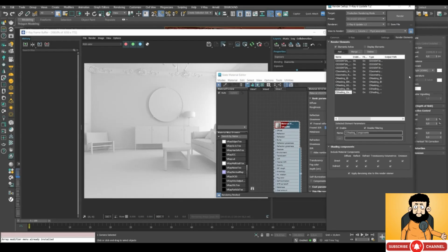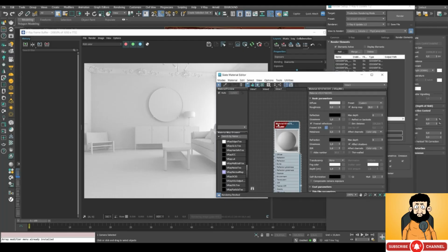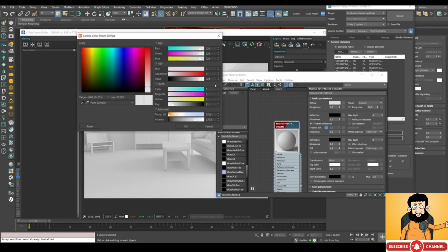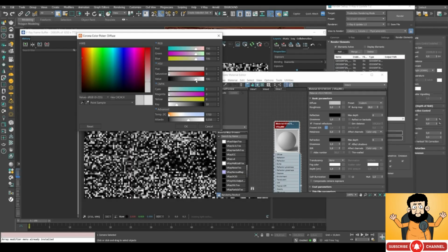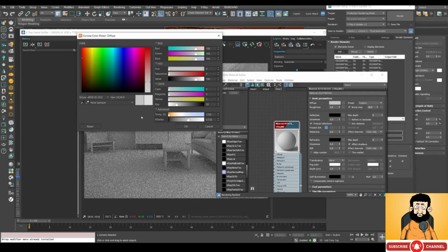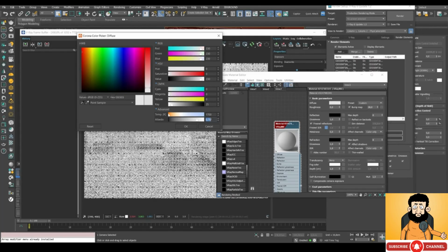As far as I know, there's no way to check the current albedo value in V-Ray. But if you happen to know how to do that, please let me know. If you have an override material, a wall material for example, its albedo shouldn't exceed 255, so you should go for a lower value. If your override material is white, once again it can be a wall material, its albedo shouldn't exceed 0.7 or 0.8 as a general rule.